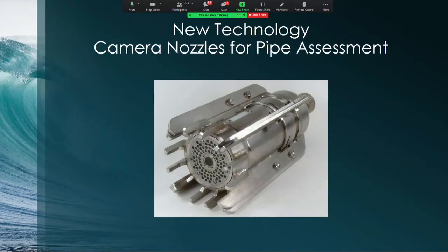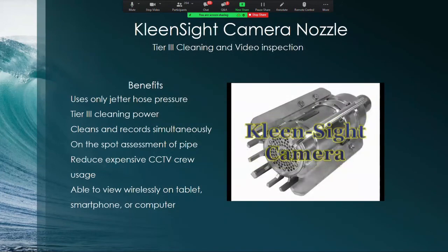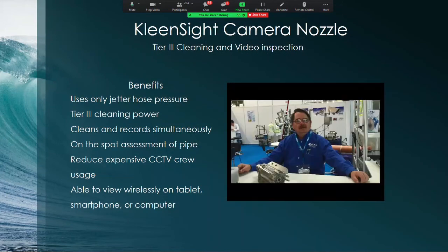We're getting near the end of this, and timing's going to be just about dead on. This is a camera built into a nozzle, or a nozzle built into a camera. Call it whichever way you want. High definition, self-leveling head, 80 LEDs in the front end, 98% efficient nozzle on the back end. It records as it cleans, and you can see the pipe pre-cleaning and after the cleaning assessment. Basically, your jetter hose becomes your...